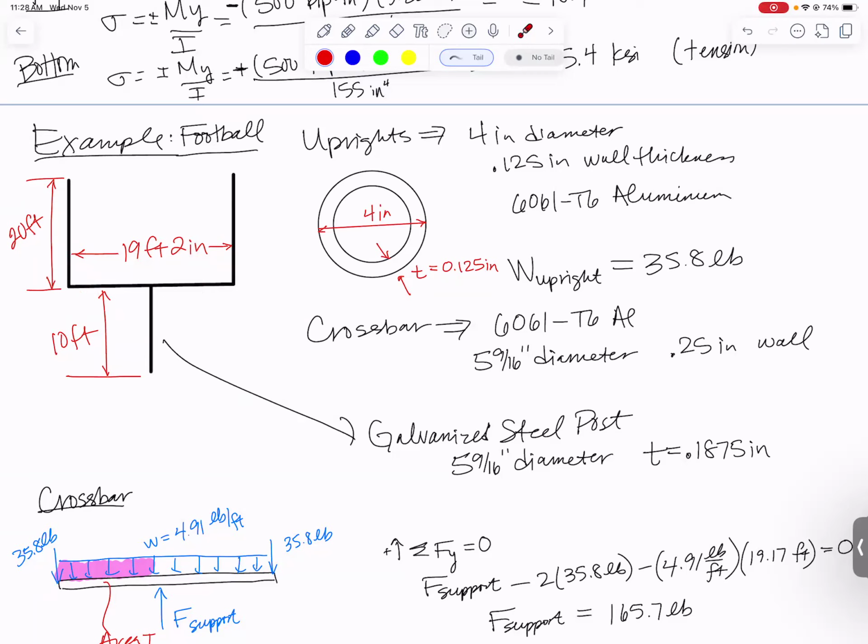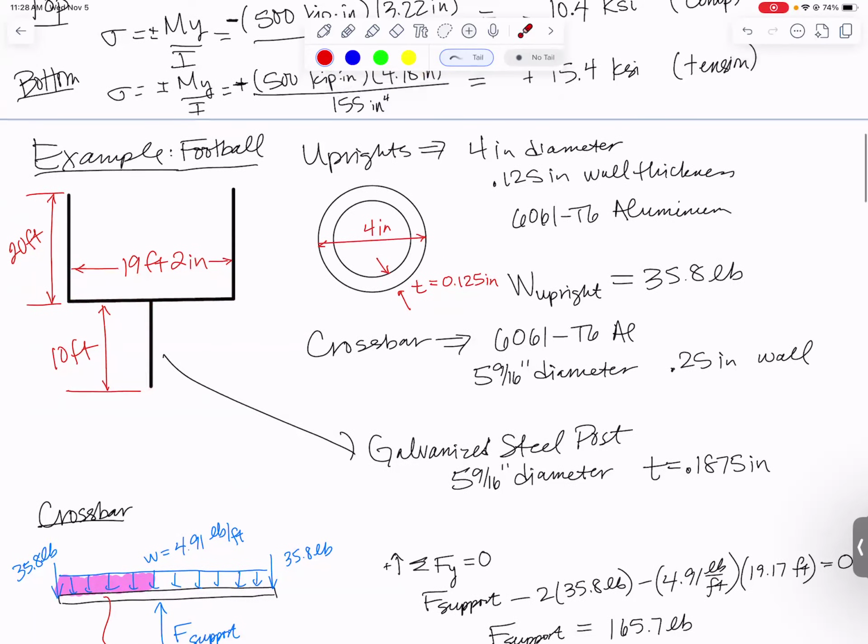Finally, if you look structurally at where these uprights tend to fail, in every video that I've been able to see that level of detail, they typically don't fail in the crossbar. They typically fail in this support post. If you looked at this on the side, if here's your upright crossbar coming out of the page at us, that support bar has this curved shape to it. And in that curved shape, it usually fails somewhere around there.